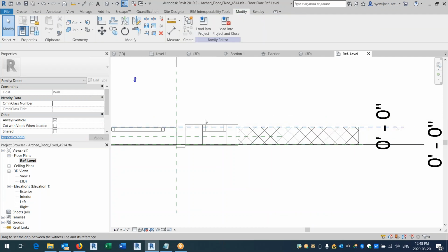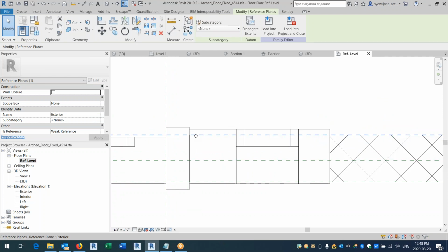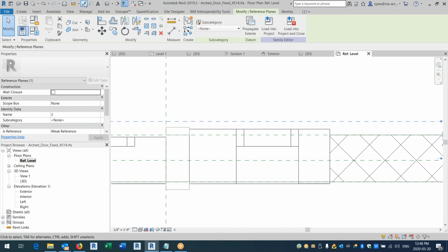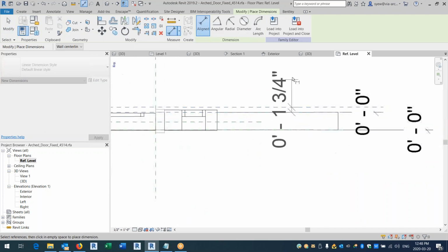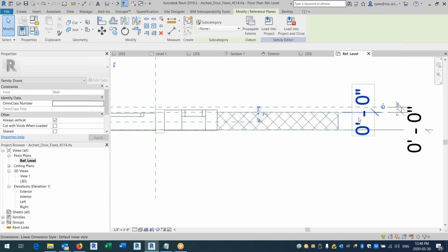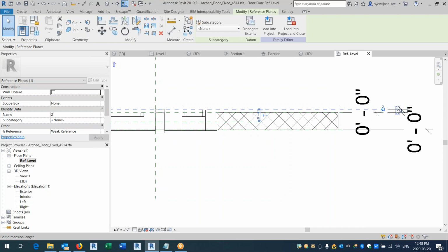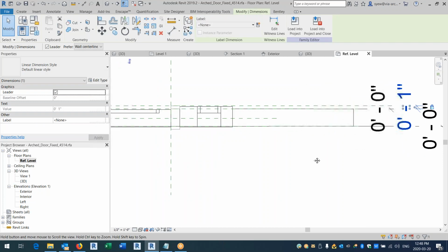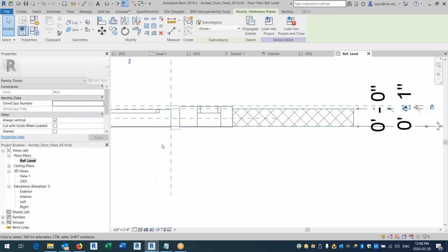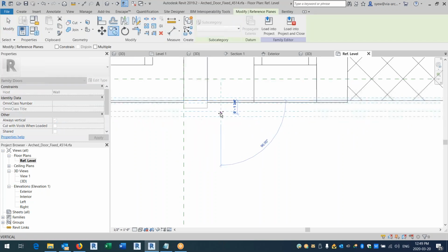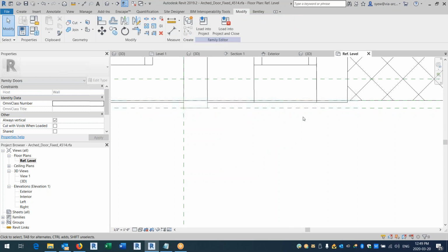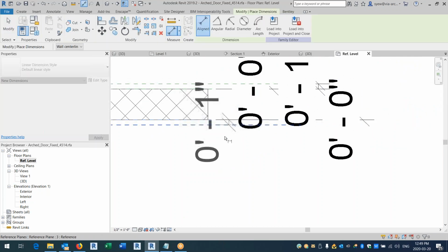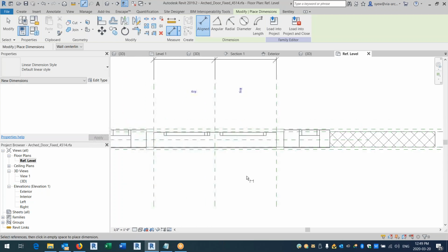The next thing you want to do, once you have that exterior and interior, is decide how deep you want this to be. So I usually say, okay, let's go 1 inch. Okay, that looks good. You can lock it or you can give it a parameter, doesn't matter. Same thing here, 1 inch. We'll go from this particular one to that one and just lock it.